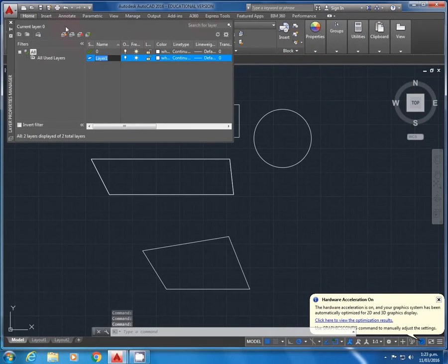And if you click this button, when you can see the tick, that means that's the layer you're working in. Because you might be working in a different layer and that screws up your entire drawing. And you can turn the different layers off and on. So if we make another layer and say this is the drawing layer, if we work in reference first,